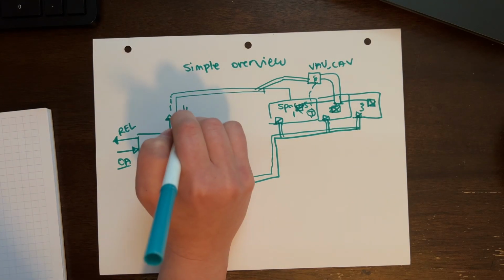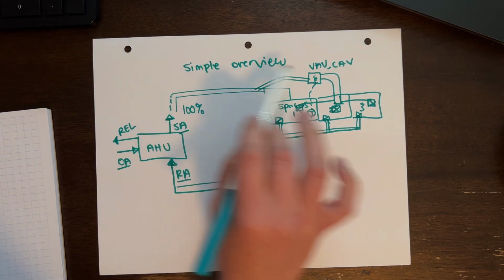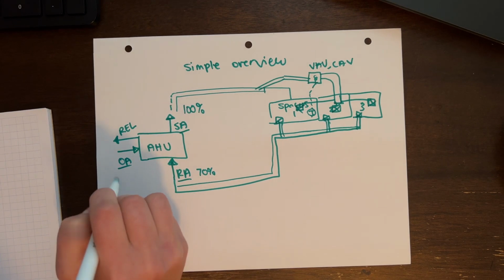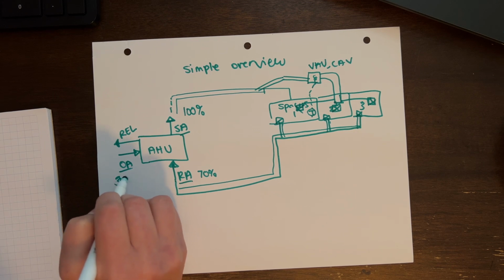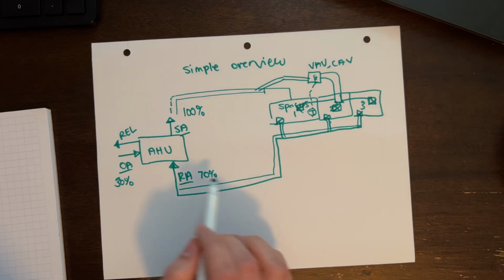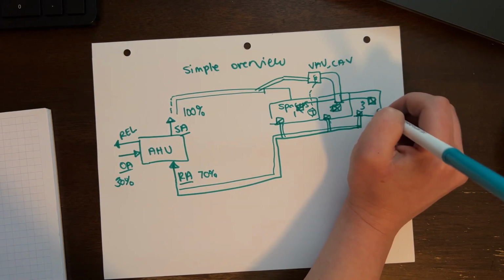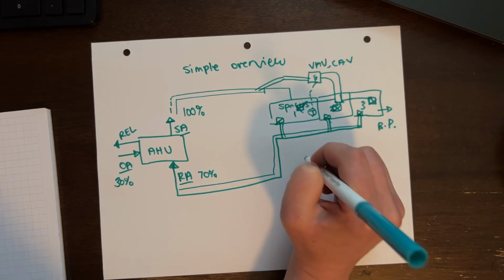Sometimes you'll always have 100% of supply air going to the space, but you'll only have 70% return air coming back. This is why you have an outside air connection. You'll probably make it up with about 30% air. And then there's your outside air. So where is that 30% air in the system? Some air is just left behind, which causes building pressure. And other air is exhausted.